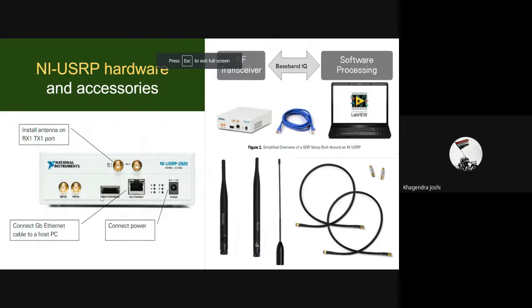See, you can consider this as a dummy device, right? It has a motherboard at the bottom where you can see all these ports are connected, and over the motherboard we have this RF daughterboard, which has these RF ports, right? Now we have to tell this particular device whether you're working as a TX or an RX. For that, everything needs to be mentioned in LabVIEW. So we have to define a port by name. If it is a transmitter code, we have to define TX1 there, right? So this device will automatically understand that yes, this particular port is being programmed, right?